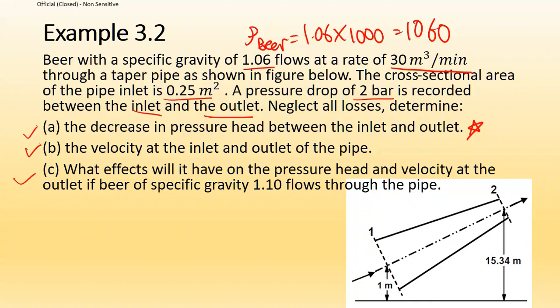At this point, I need to point out that even though we have mentioned something called the total head, we are not going to confuse things. Whatever we measure at 1 and at 2 is simply just the pressure, the static pressure. The total head will not come out at all. Total head is only in the equation itself.